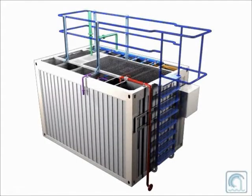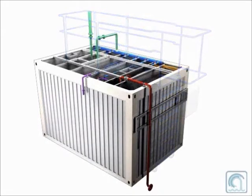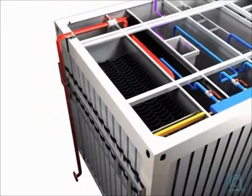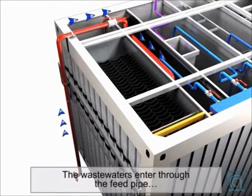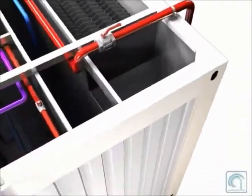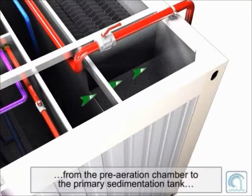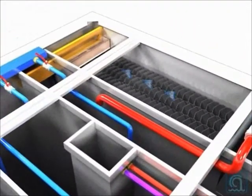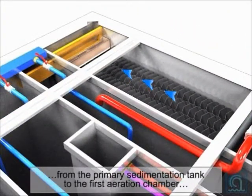This video describes the flow of wastewater through the package treatment plant. The influent coming from the lift station enters the pre-aeration chamber through the feed pipe highlighted in red. From the pre-aeration chamber, the wastewater enters the primary sedimentation tank, flowing through the passage shown by the arrows. After passing through the lamella settler, the wastewater goes through the bypass into the first aeration chamber.